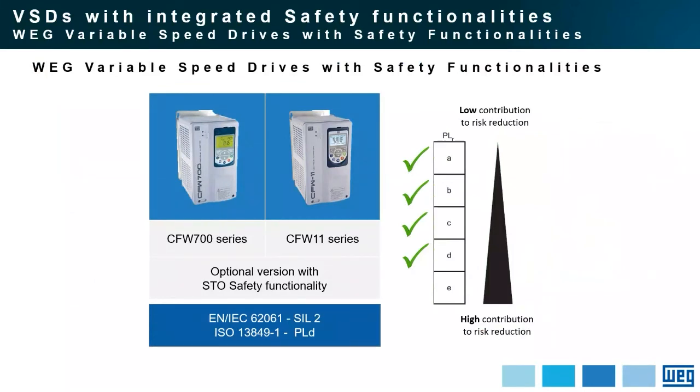And what are the WEG variable speed drives that include such safety functionalities? I will say here that the CFW700 series and the CFW11 series have the optional version with the STO functionality, complying with both IEC and ISO standards.